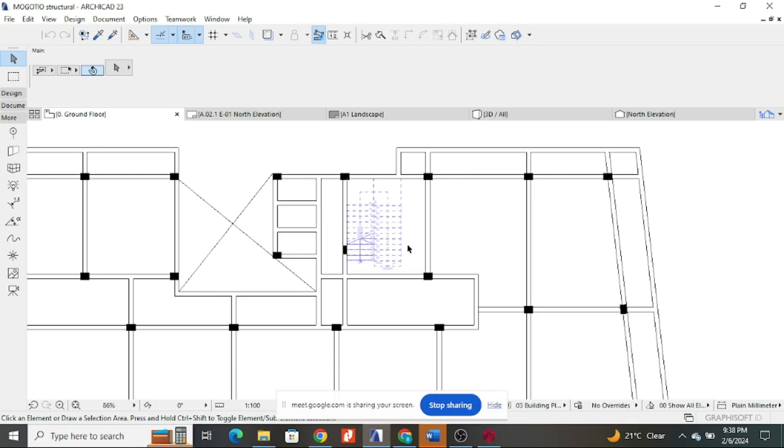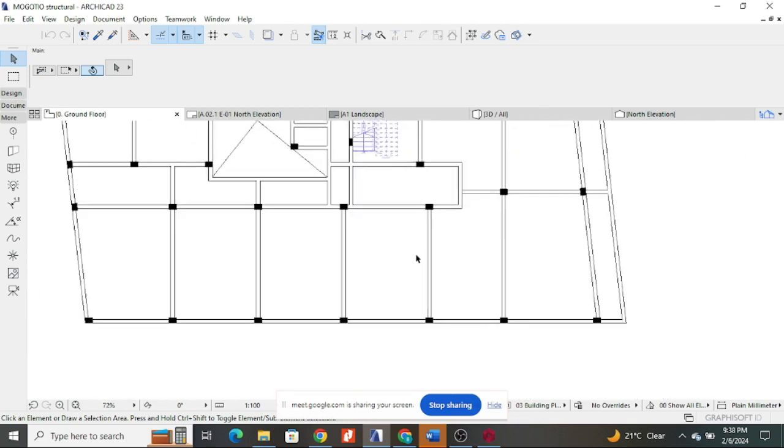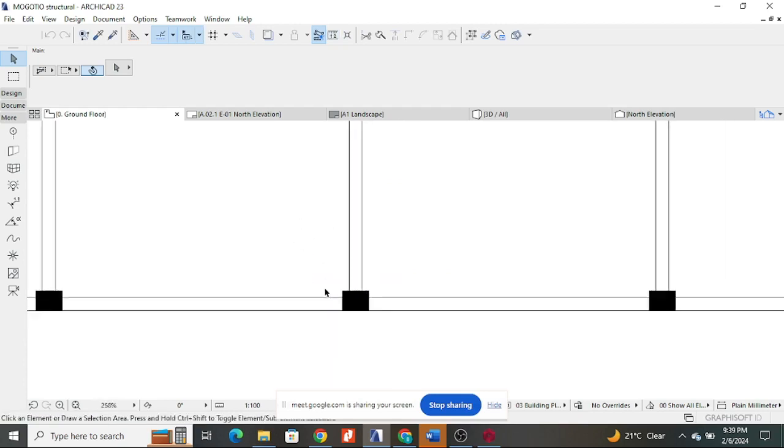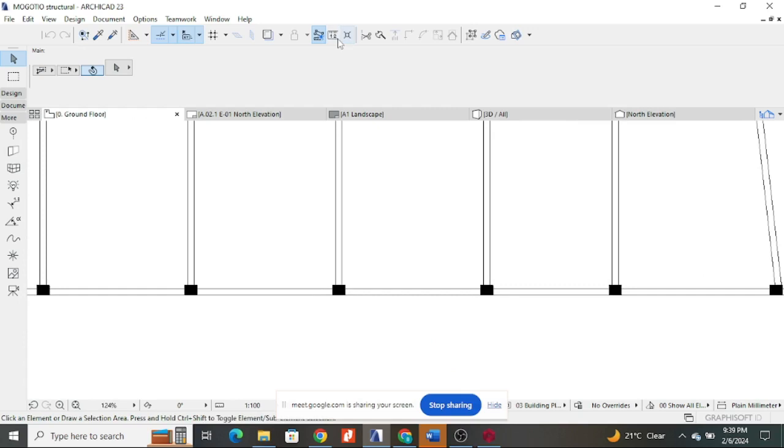Okay. Next, after you've determined your levels and your heights, that will help you do a preliminary sizing of your columns. Because this is a commercial building, it is almost 5 stories high, I did 400 by 300 columns. Before we proceed, yes.